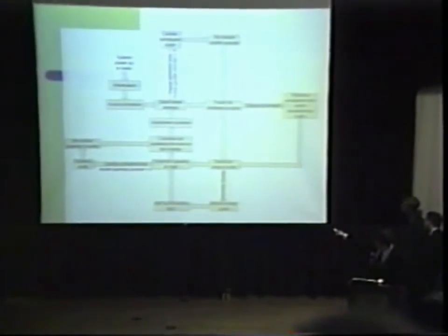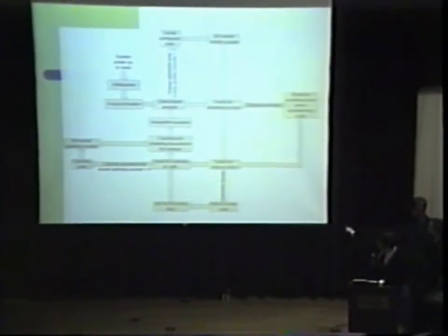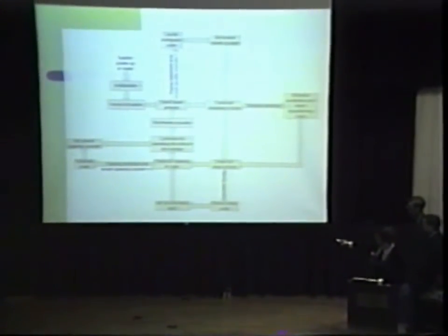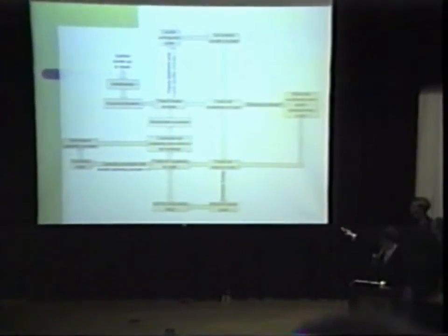After the sound activation part, the code jumps into a loop here. This is the central loop where most of the stuff happens. Inside this loop, it's constantly checking sensors to meet certain conditions. Also inside this loop is a central controller to keep the robot centered in the hallway. These conditions here checked for things such as if a flame was detected and a certain counter equaled 0.